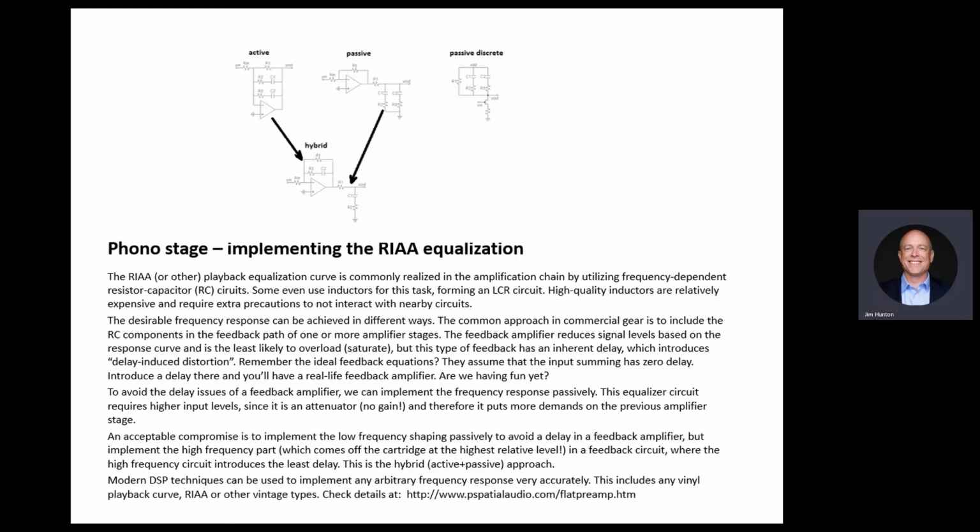All of your circuits there are inverting, so that means the input impedance is low. In the normal phono preamp, you want a higher input impedance, so you go on the plus input. Again, this is not necessarily so. There are too many applications where people go in the negative input. No, not necessarily.